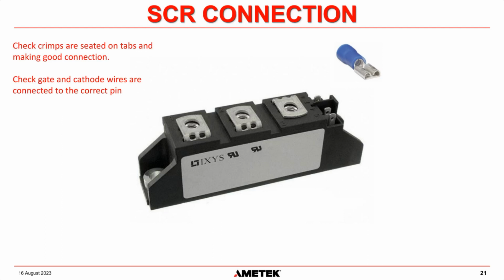Just be very careful. And there are some circumstances where internally within the SCR itself, the connection here is not physically connected to the internals of the SCR. The connection has broken. That's very difficult to tell. It's a very difficult test to find that. So in truth, all you're looking for when you suspect there's an SCR issue is that the terminals are connected correctly.